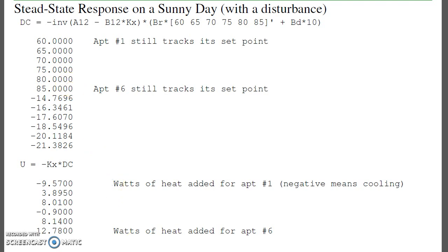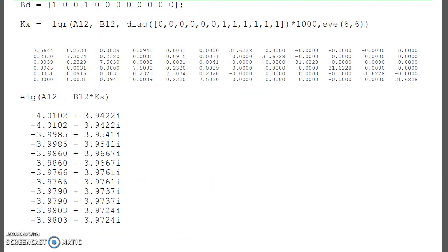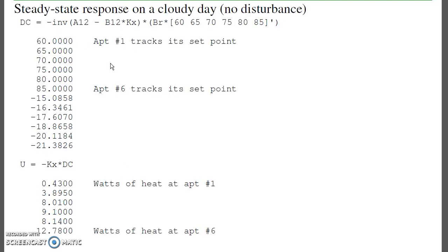The disadvantage of this method is right here. With LQR techniques, I wind up with 72 feedback gains. If I want to set certain gains to 0, too bad. When I use LQR techniques, I'm going to wind up with a full matrix, all 72 feedback gains. But with that, that also illustrates the principle. If you want to control n outputs, I need n inputs. And with servo-compensators, I can force the DC gain to 1 for each of those outputs.